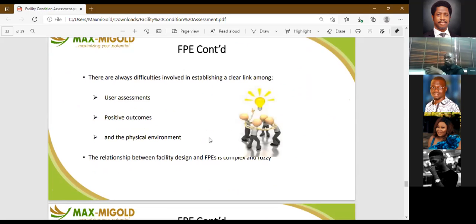So when you use the end user survey, the survey will be all about replacing that asset, but your budget at hand cannot support that kind of capital expenditure at that period in time. What do you do? You could go for improvement, and your improvement could require comprehensive repair and maintenance on that same asset.